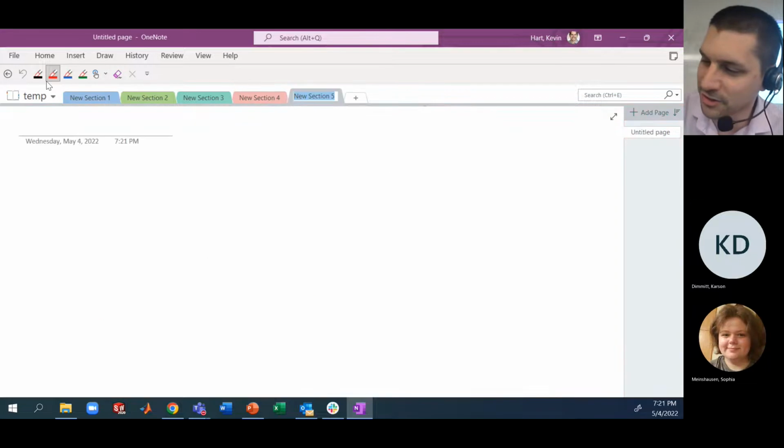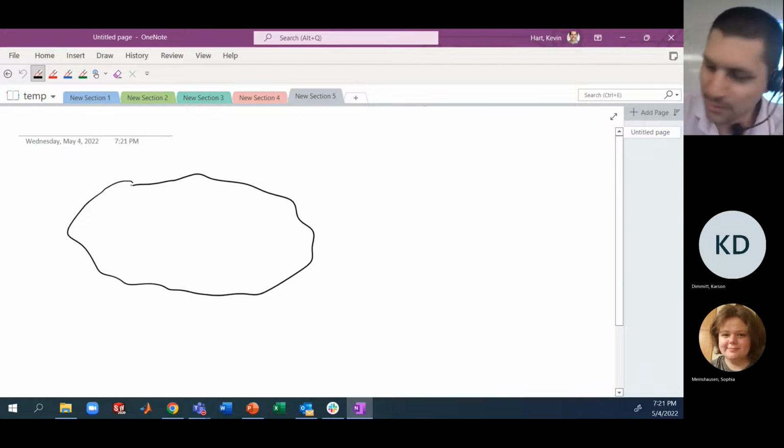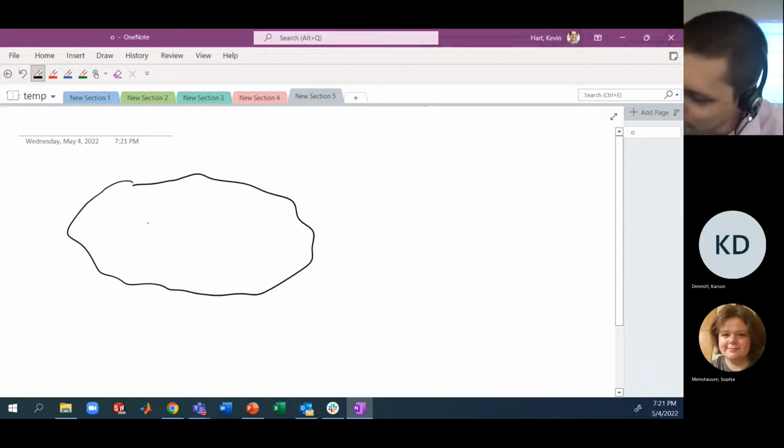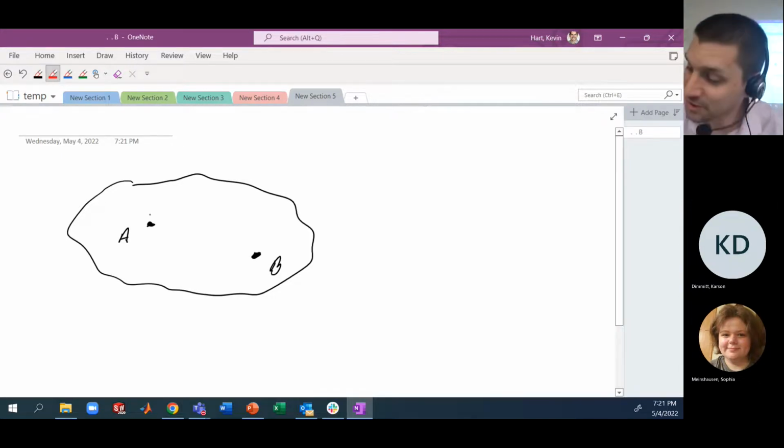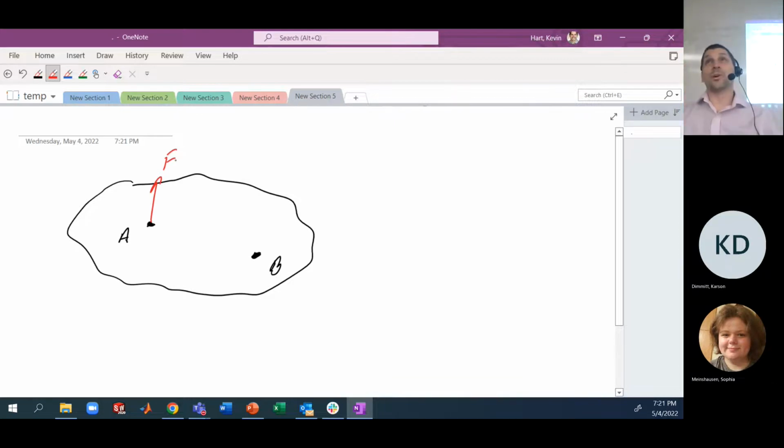Let's have a little aside here for just a second to clarify Mr. Jensen's question. World famous, say it with me, mechanics potato. That's right. And let's say we have 2 points on this body. Point number 1, point number 2. Okay, let's say A and B. All right, let's say that we have some force on A that is capital F. All right, and we want an equivalent force couple system at B that represents what's happening at that portion of the body if we needed to pick up that force at A and relocate it at B.